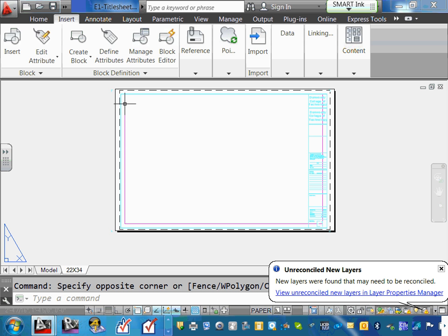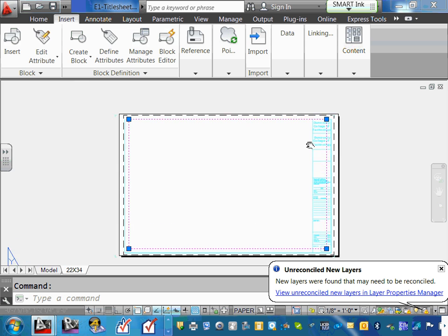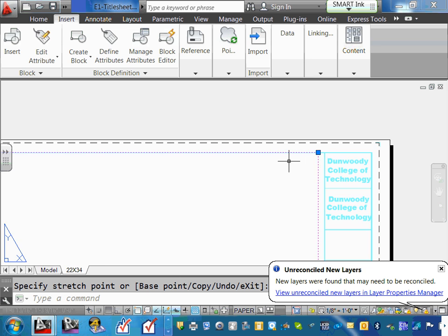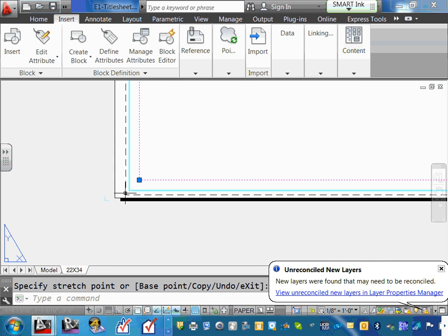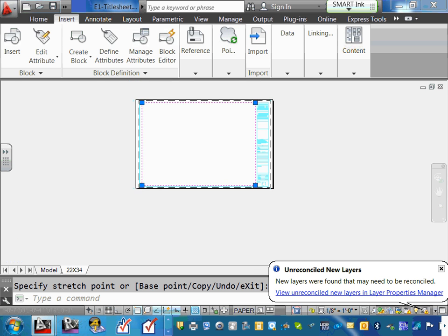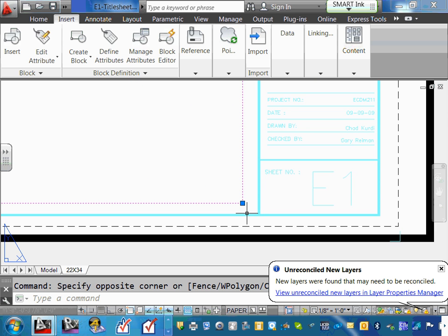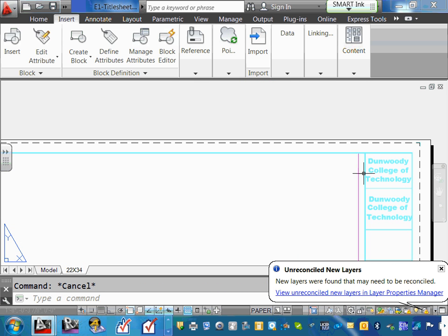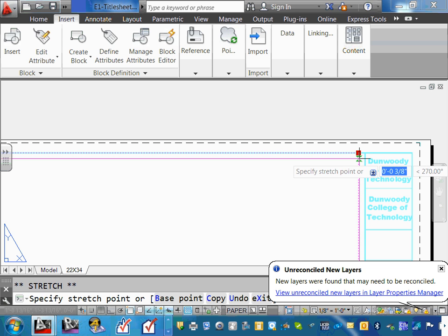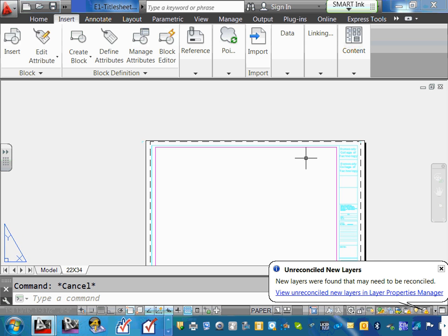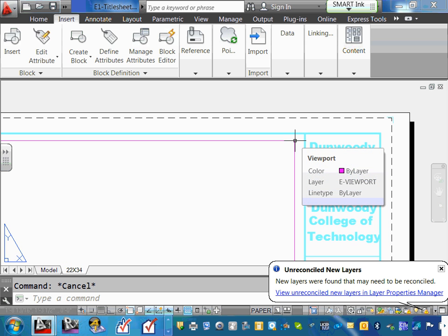Viewport would shrink that. Now the viewport, click on your viewport, guys, and make sure your viewport fits within the printing parameter of your page. Personally, guys, I don't like to attach it to the tab block. You don't want to attach it to the viewport, to the print, because then you can't pick it up sometimes. So just slightly underneath it. You guys see what I'm doing?